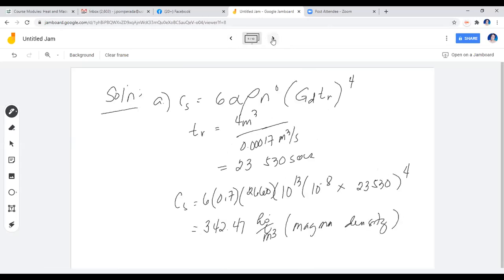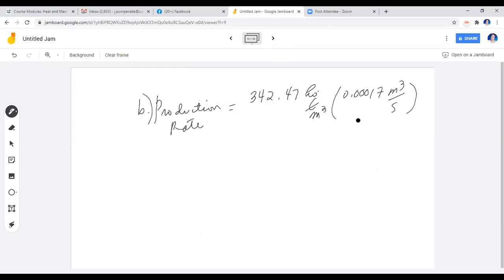So in this case, you will have now a production rate in mass per unit time. Using the principle that your crystals will be coming from the magma, because your crystal is just a separation of your liquor from the magma, and you have already the crystal. So in this case, you have 0.0582 kilograms per second. That's very small because it's per second.